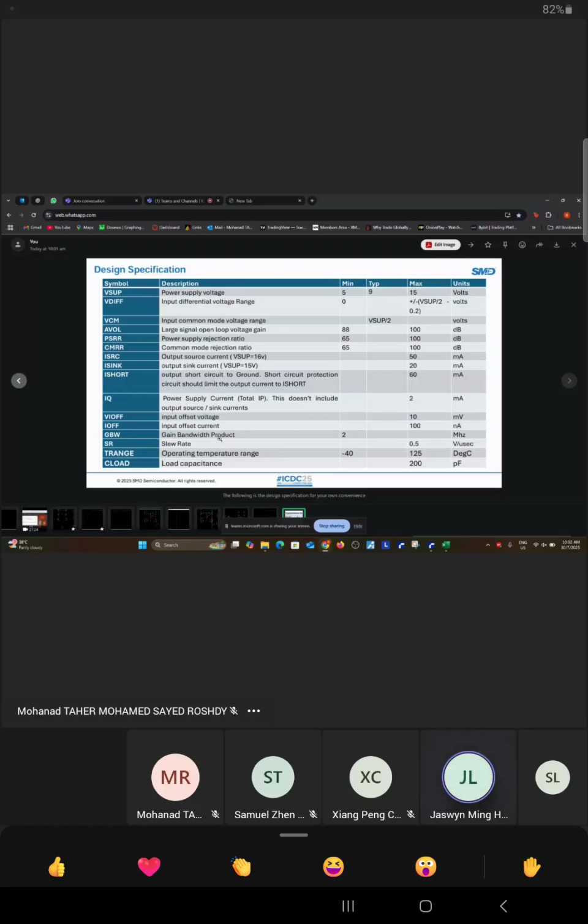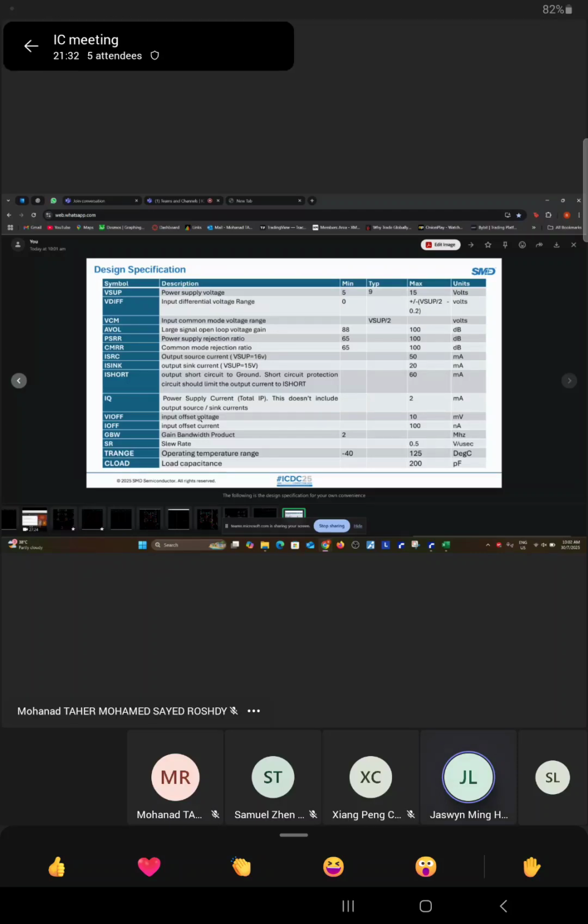They also give us an input offset here. Should we also include it? Input offset, yeah, the maximum is 10 milli. You can do it later on. I would say it's better to keep all this constant first, which means you put the offset at 0 first. You test some of the parameters, then step by step. If you put in too much at the same time, I don't think that works. That's the industrial practice. Usually you test just one parameter first.